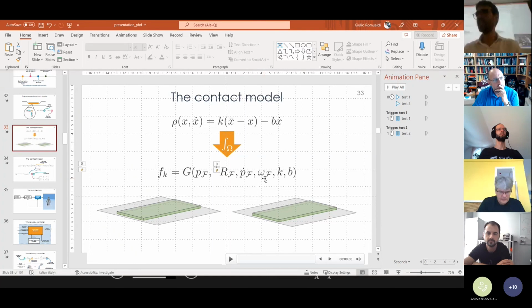So for instance, the foot. It's not possible, in order to control the force, we would need to directly control, for instance, the velocity. But in a torque control strategy, what you can change is the acceleration. So if we compute the time derivative of these, it will have some terms that depend on the acceleration. That is actually the linear acceleration and the angular acceleration, and those are considered inside the optimization problem.